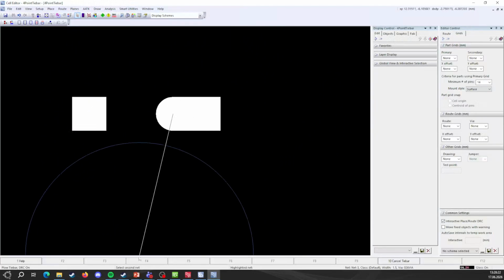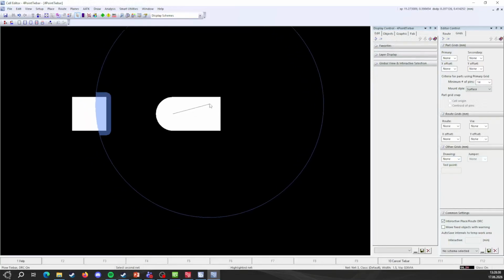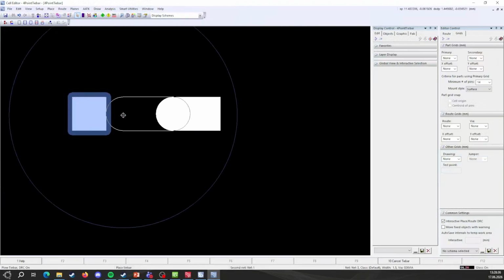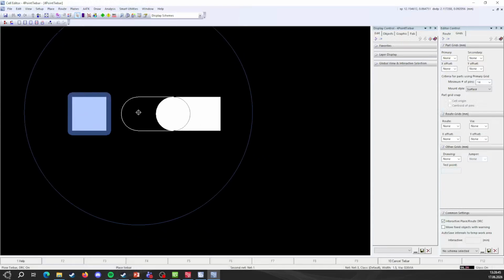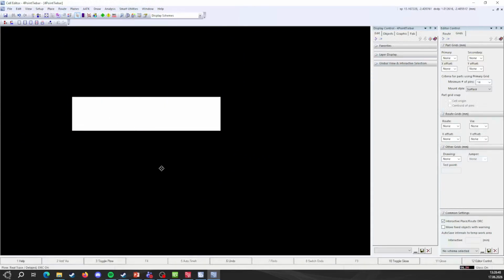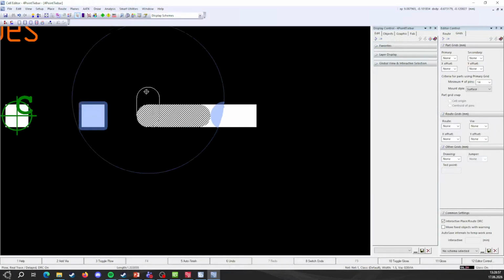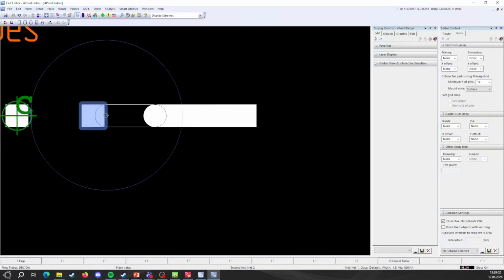This is basically how it's called, a hint for you. Select the second net. So it's asking which nets we actually want to net short. The first of them is the net of that path, and the second one, click here. Now we place in tiebar, as you can see in the status at the bottom. So I can create a small tiebar and then finish it with my normal trace. You need to repeat this process for other SMD paths. So it means start to plow, T, choose the pin,